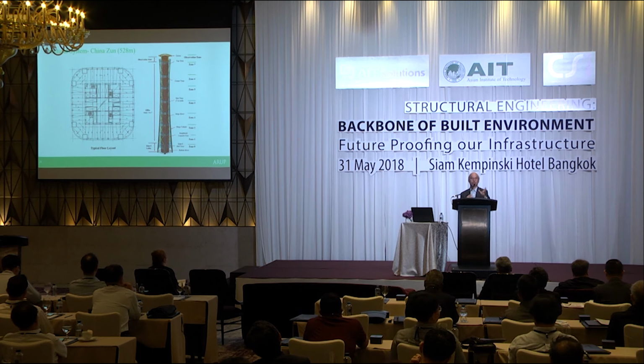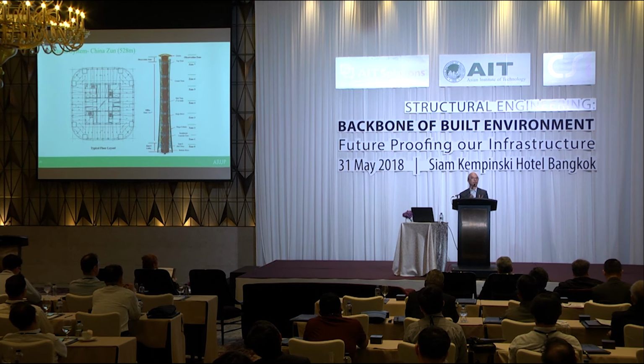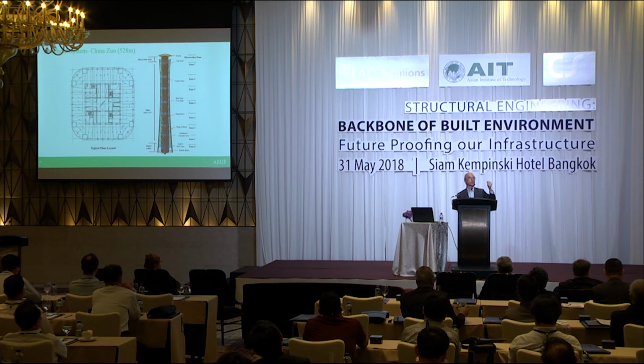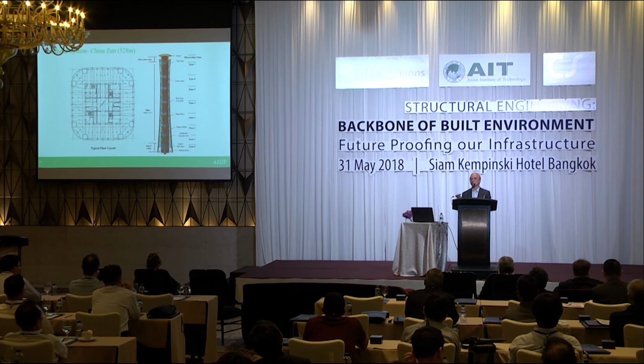Well, from a structural point of view, a lot of structural engineers say it doesn't make sense because you're putting more mass at the top, you make more drift, you need more stiffness. But in comparison with the whole cost of the project, we can strike a balance again, right? How much area we put on top, how much stiffness or extra cost we need to put in the structure, which one is the best, okay?